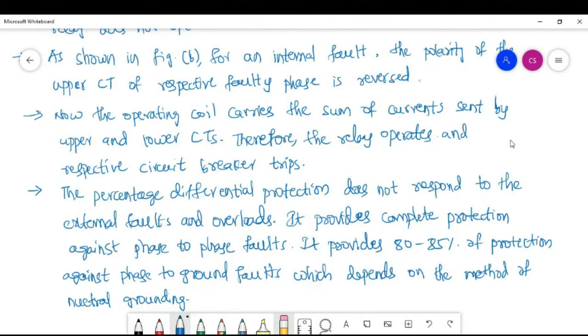Either it is solidly grounded, or isolated, or resistance grounded, or reactance grounded. When we discussed the per unit system, we indicated it like this. So this is a generator, and we indicated reactance grounded like this. Sometimes we indicated resistance grounded, sometimes solidly grounded, and sometimes the isolated case we did not indicate.